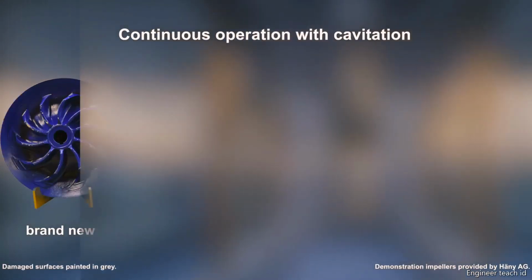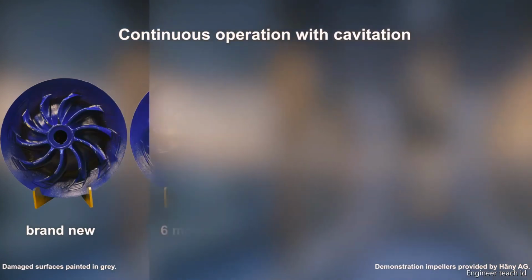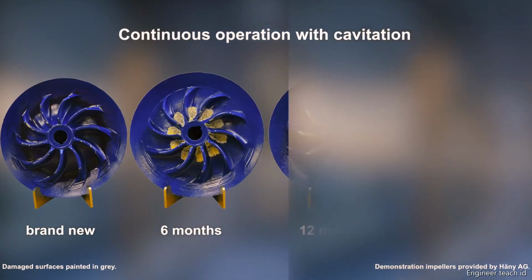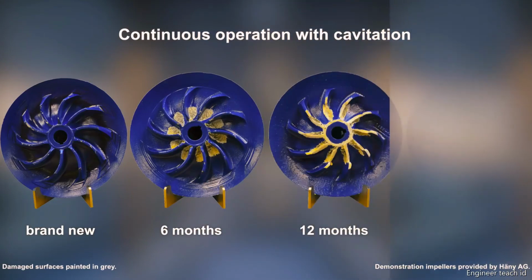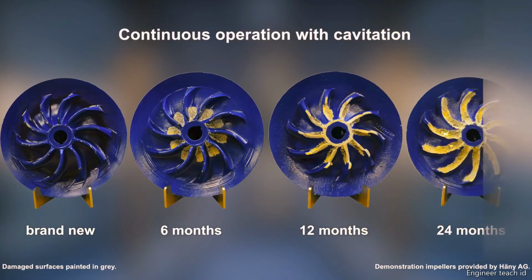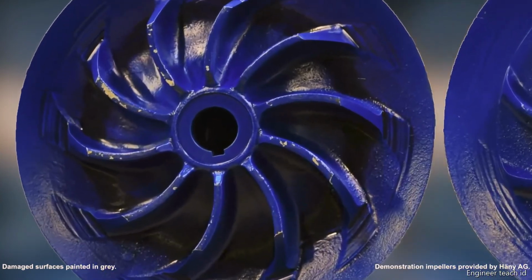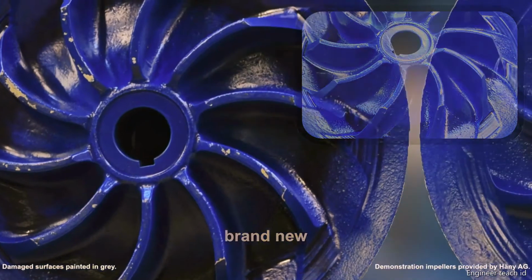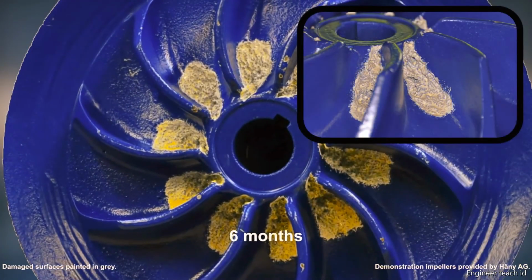A brand new impeller to the left in comparison with an impeller having been continuously exposed to cavitation during 6 months, another impeller with damage from 12 months operation in cavitation, and one from 24 months. The new impeller shows the geometry as it should be under normal operation without cavitation. After 6 months of operation under cavitation, material has been eroded in the center of the wheel. The respective areas are highlighted with grey color. The impeller blades are undamaged.